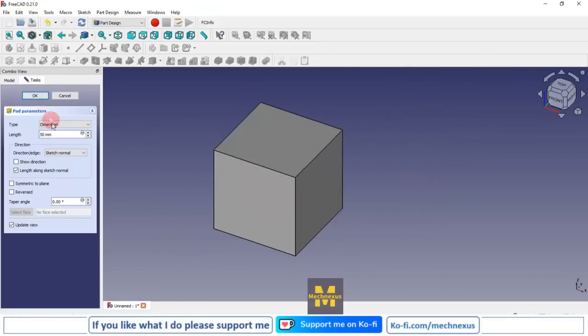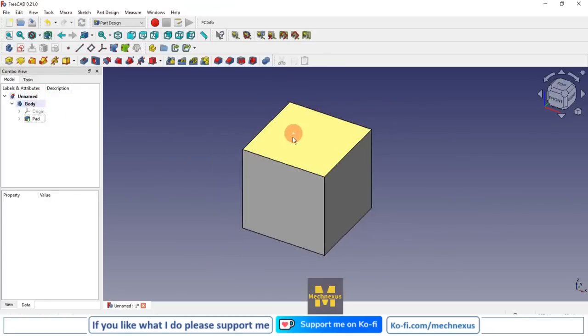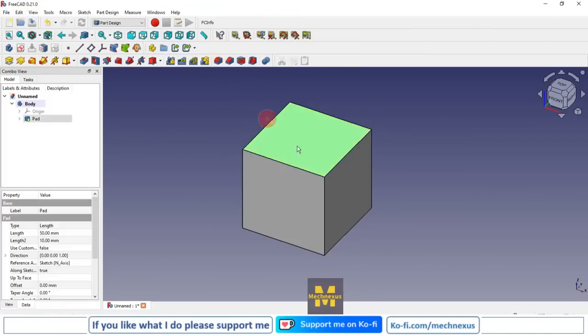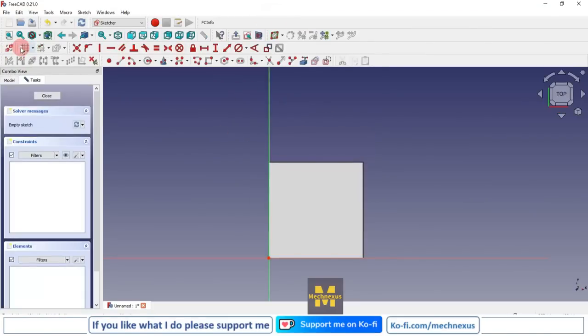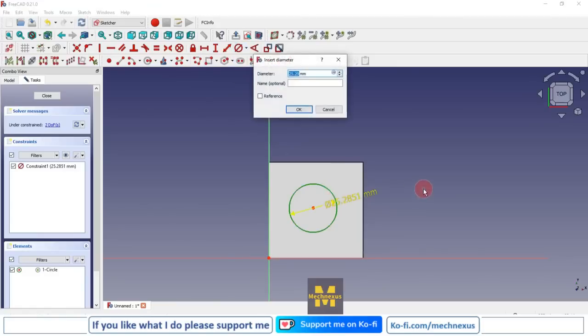Now I will close my sketch, and now we will give the holes and understand the different types of hole feature available in FreeCAD. So I will select this top face and create a sketch, and here I create a circle and give a rough diameter of 20 mm.